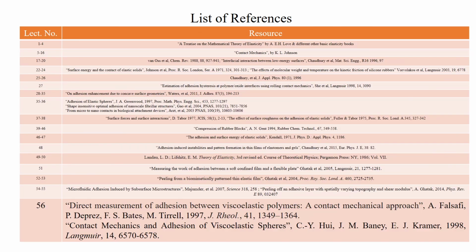In the last lecture we discussed a thin layer of adhesive with spatially varying modulus, from which a flexible plate is lifted off, and what kind of torque is required to propagate the crack at the interface. We derived those equations, which were to be solved numerically, and we also presented some results. These results were in my paper.